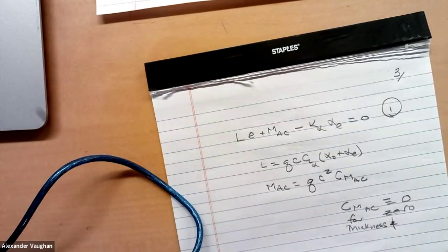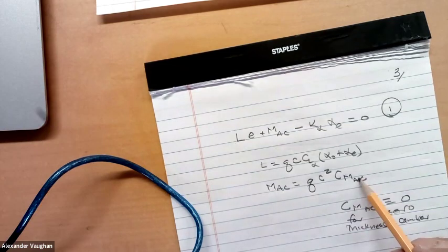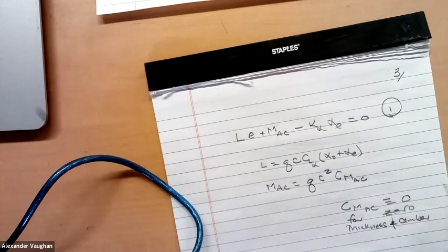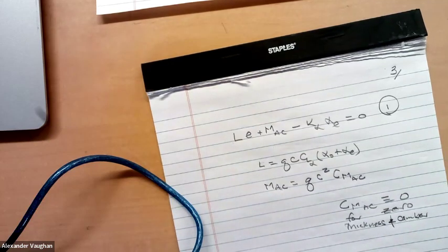The aerodynamicists call it camber. We're talking about curvature, right? Camber. So we can carry this term along. It turns out it doesn't impact divergence. And if for some reason later on we want to look at an airfoil that initially has a built-in curvature, then we would put in an appropriate number for this. We ask our aerodynamics friend, what is that number? And they tell us.